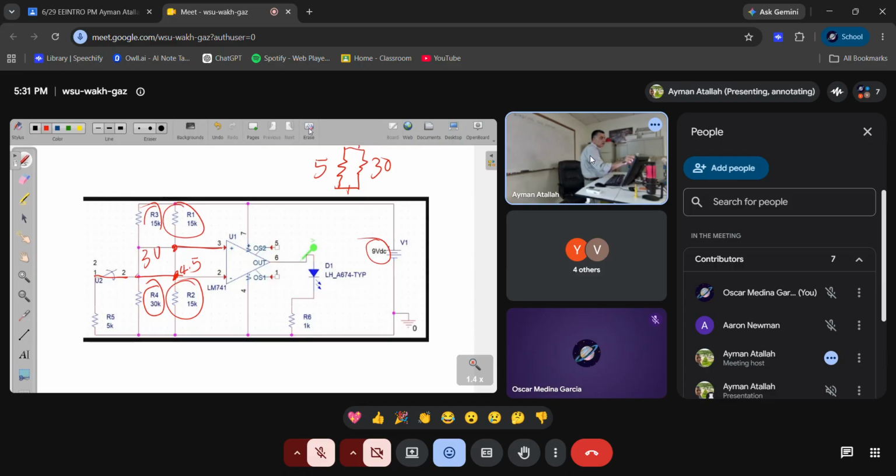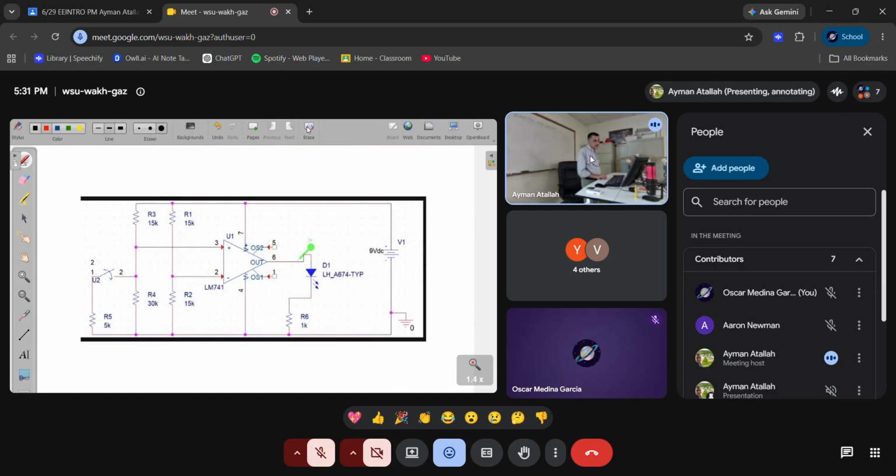Okay. So let us build this with PSpice right now. We have everything. Make sure to put 2 seconds here. We are going to use transient simulation for 4 seconds. You just write 4, and the maximum step size 1 milli, 1M. And let us see what will happen to the voltage here.